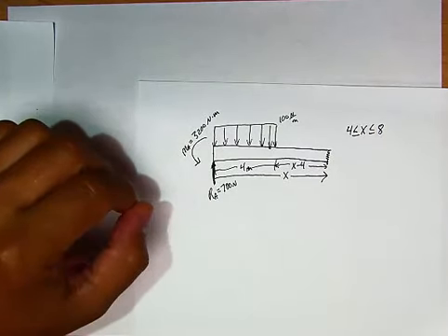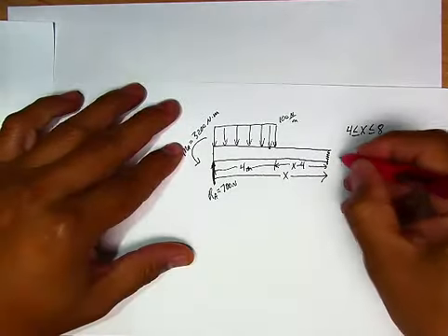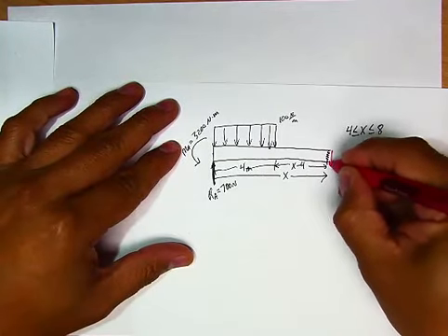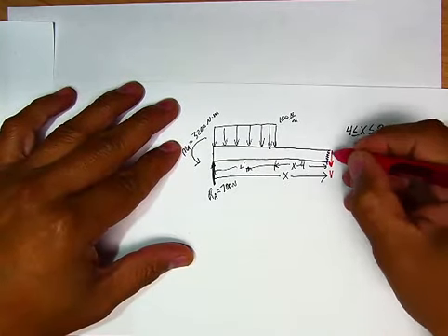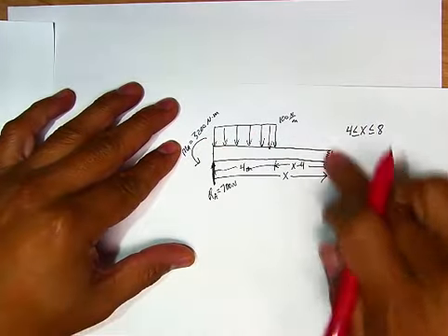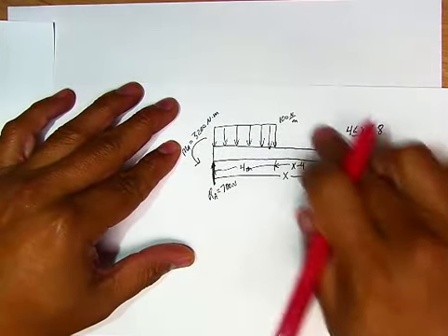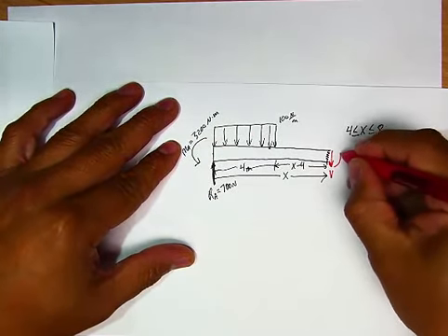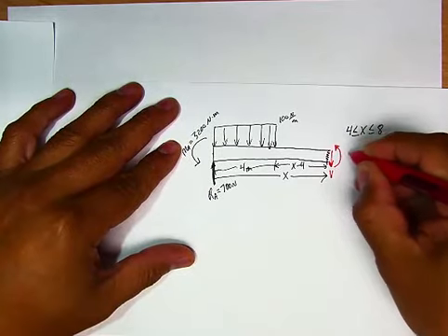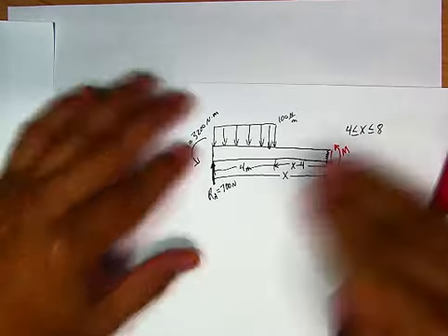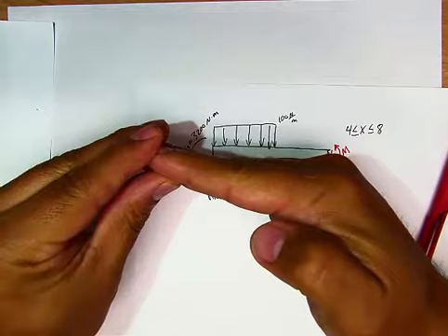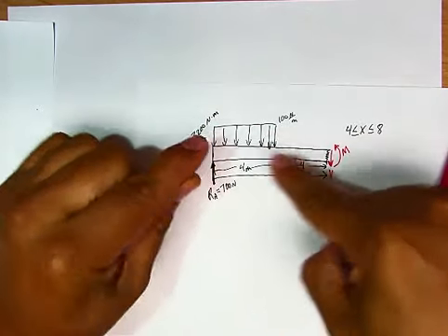All right. Now, let's go ahead and draw our shear. We always want to make the shear so that it causes a clockwise rotation. And then we want to draw our moment that makes a happy face. So it makes you draw a moment, happy face.